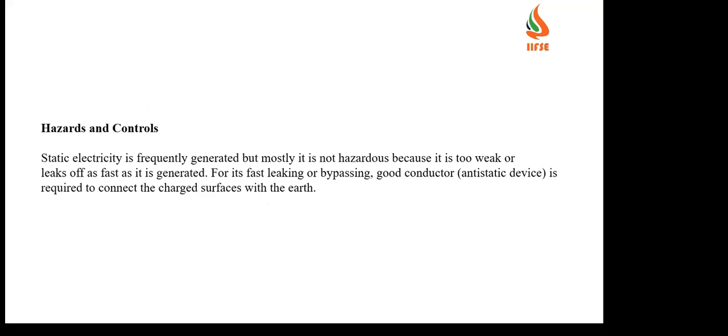Now we'll see some of the hazards and controls. What is the hazard caused by static electricity, and how can we prevent it? Static electricity is frequently generated, but mostly it is not hazardous because it is too weak or leaks off as fast as it is generated. How fast it generates, in the same way, just as fast it will get discharged.